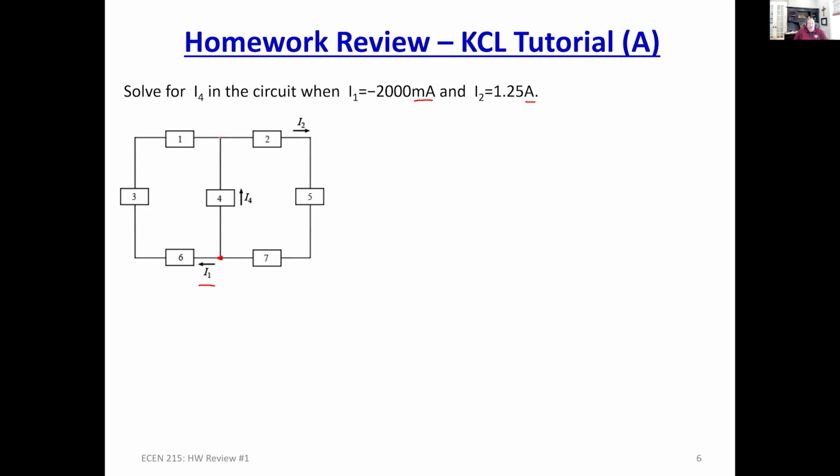Now for my online students, because I know I hammered this really hard the last couple of lecture days in the live class, one thing to make sure you pay attention to is a node is not a dot. For everyone who was in class on Wednesday live, I know I'm beating a dead horse. But again, this is not graphical analysis. This is basically just electrical connections. Wherever electrical devices come together, that is a node. This is going to trip you up on the test if you don't get this right.